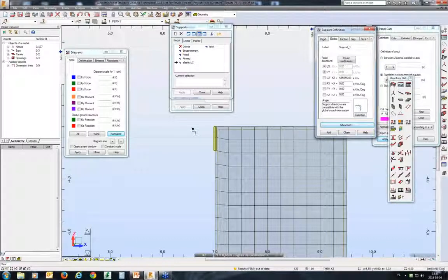In a walls and floors model using the same mesh settings, the mesh result is different depending on the order you mesh the model: first mesh walls, then floors, or first floors, then walls. What is the recommended sequence of meshing? Francois responded that maybe the smallest panels, like the walls with an edge fully included in a bigger panel, a slab for example, should be meshed first.